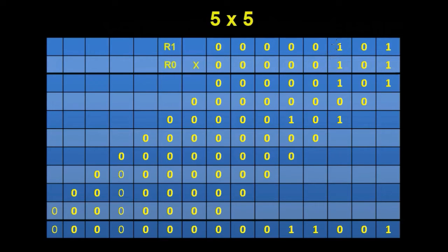And then we can go through the same process again. We can check and see whether the value is a 1. If it's a 1, again we just add the value on to the contents of register R2. If it's a 0, then we don't add anything on. All we do is shift again to the left onto the next significant bit up, and we continue working around that process until we're completed, and we should get the final answer, which in this case will be the value 11001. Now, it's difficult to explain in words, and we'll see if we can work our way through it, and it might become more apparent what's happening.